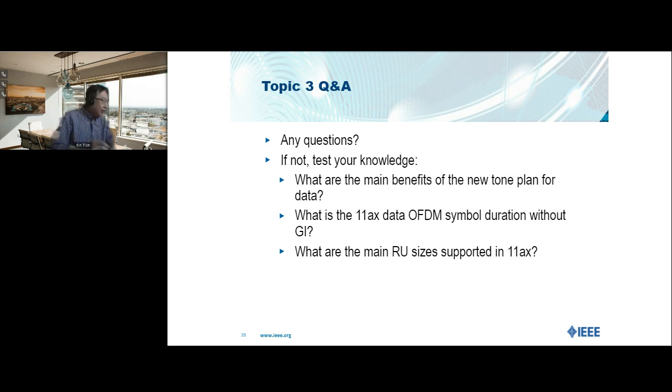As I mentioned, the tone basically refers to one of the FFT bins, because in OFDM essentially you take data symbols, then you take the FFT. For example, with a 256 FFT, each FFT bin is called an FFT tone.